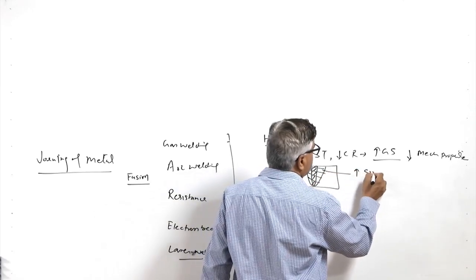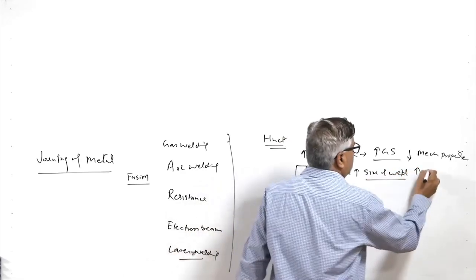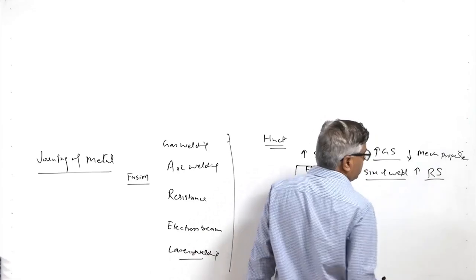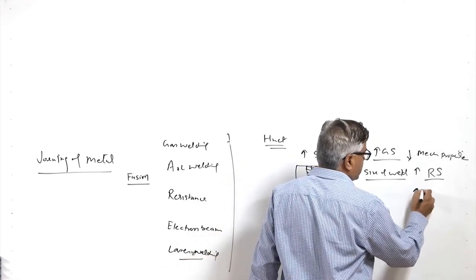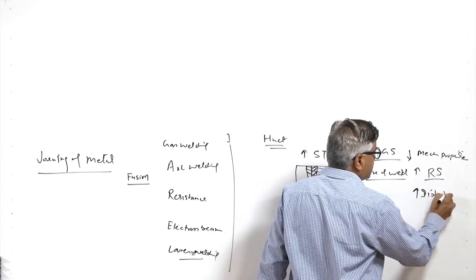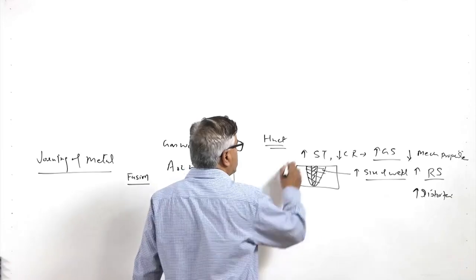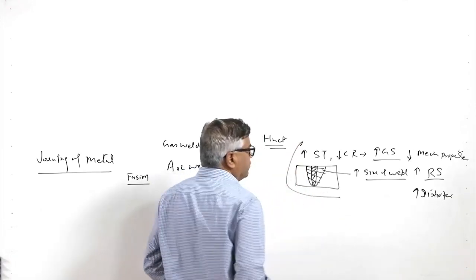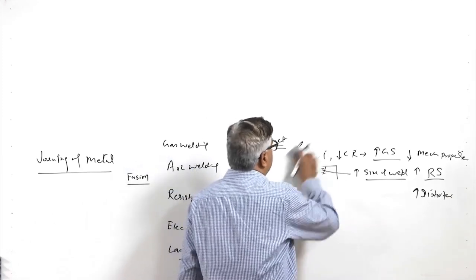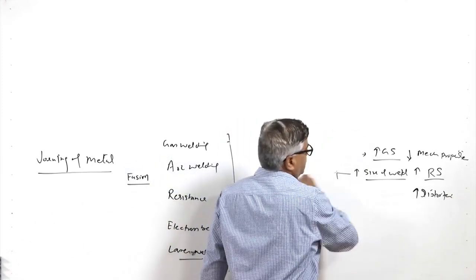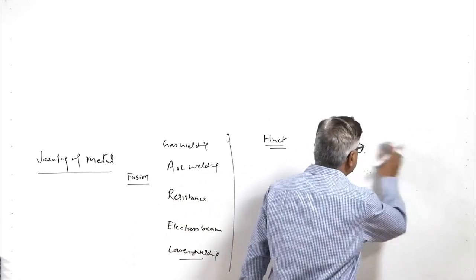Increasing the size of the weld increases the residual stresses being developed around the weld pool, and which also increases the distortion tendency in the weld. So, in order to deal with these issues, it is always preferred that the heat input being supplied during the welding is as less as possible, while the metallic continuity and metallurgical continuity is realized during the welding.